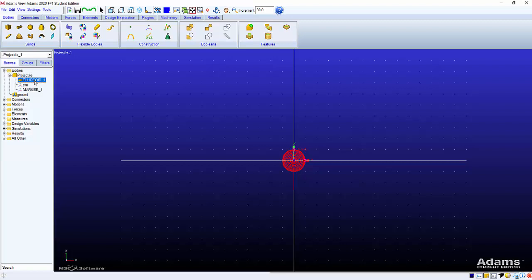let's first change the name. So I'm going to call this ellipsoid a sphere. In order to change the name, again, you can click, it will blink, and you can overwrite, or you can right click and select rename. So here I am going to change this, make it sphere. Click OK. You can see the sphere has changed. Now, as you can see, you can also right click the sphere and there is modify. This modify is going to modify the properties of the sphere. We'll talk about this later on.